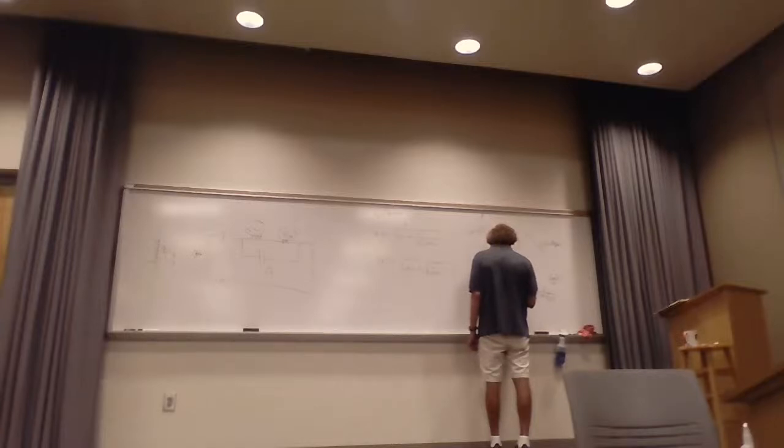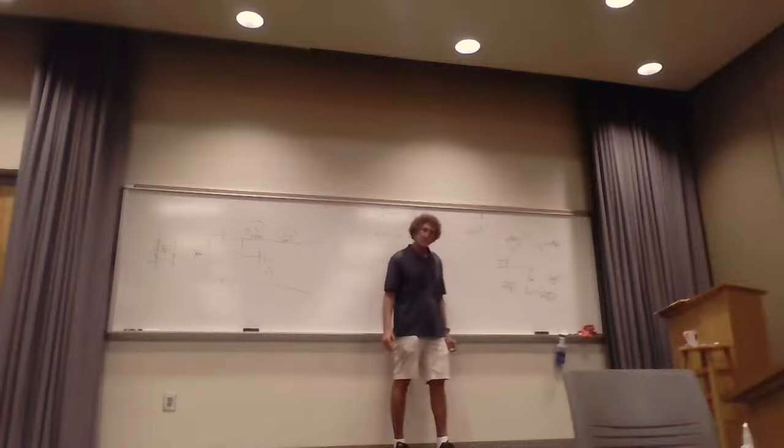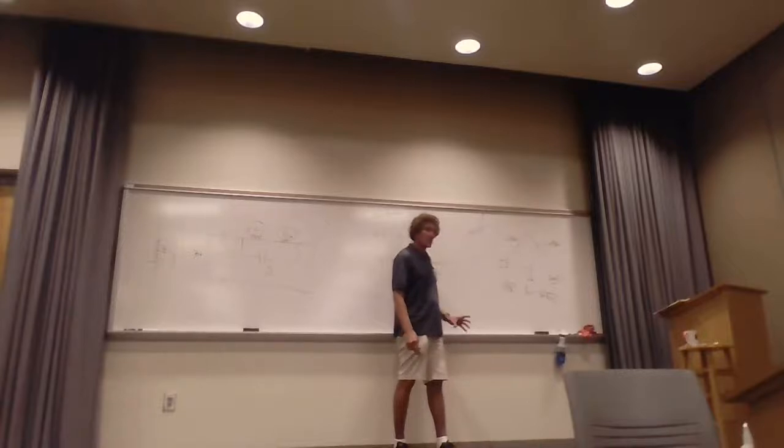And then it's really L over R, you can do it this way, that would be that lower frequency there. You could put R on top and have R over 2 pi L, but it's usually 1 over 2 pi L over R, because L over R is the time constant for an LR circuit, and 1 over RC is the time constant for an RC circuit. Do y'all remember that? That's the only reason.